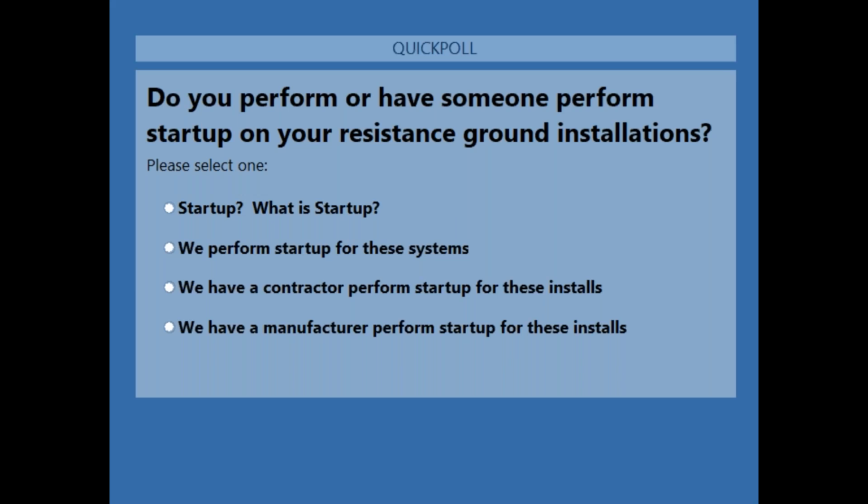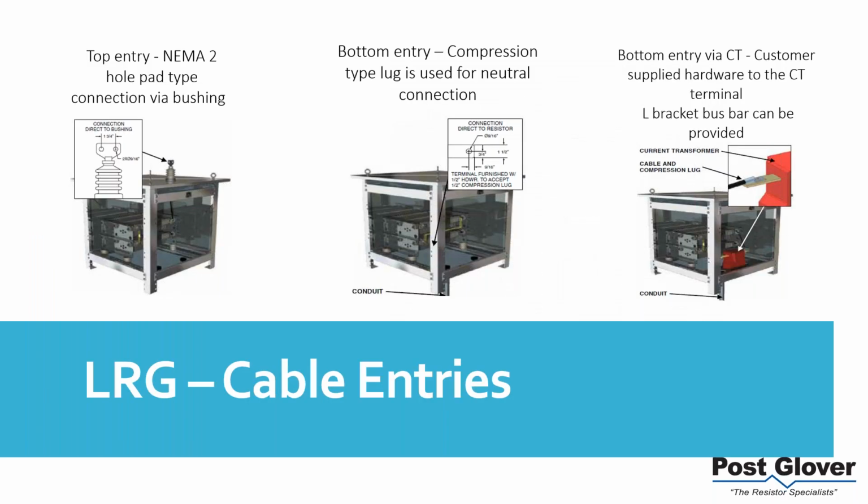All right, so let's move on to the second section. In terms of cable entries, there are different ways to install the system, based on your system, where the cables are incoming, and what kind of cables you'd want to use. I would say the top entry is very popular for situations where you have large cable coming through. There's not really going to be any room to bend that wire through. This may not be needed, as the ground wire may be smaller than you're thinking. Just go back to the table I showed before.